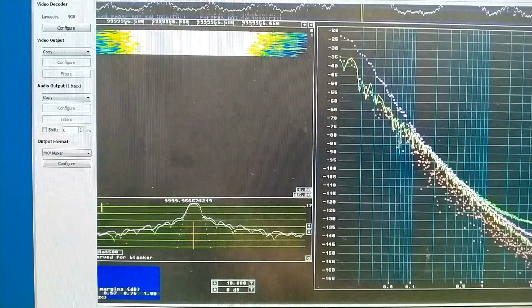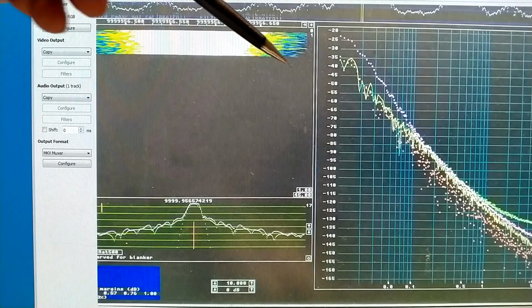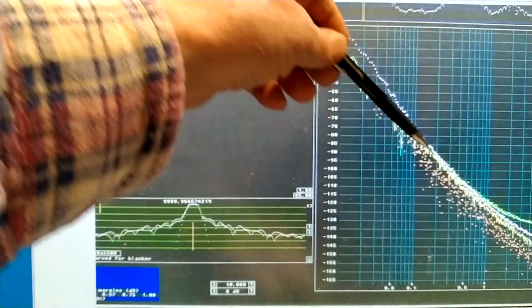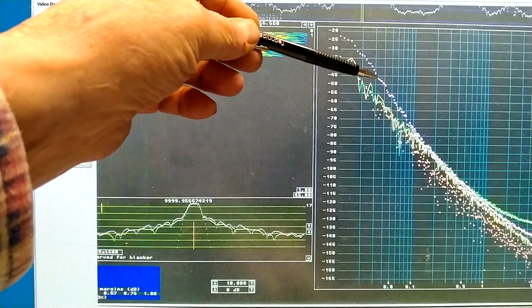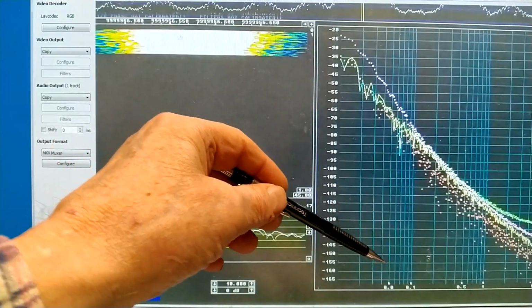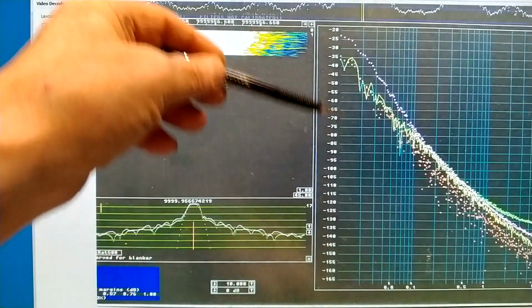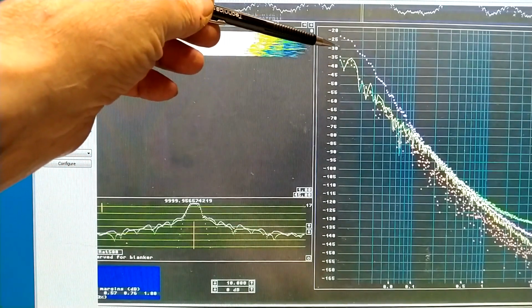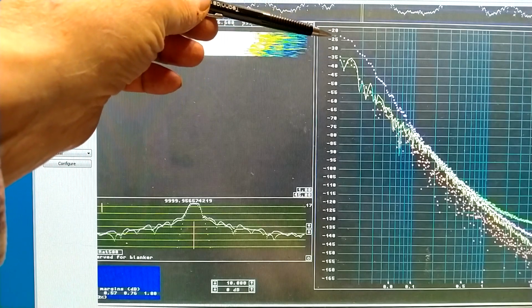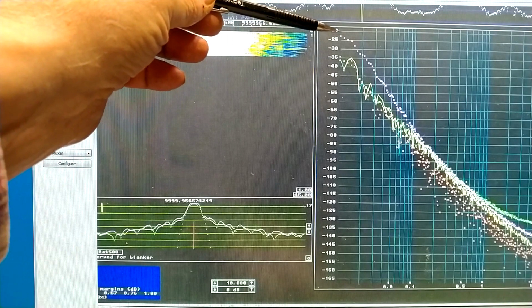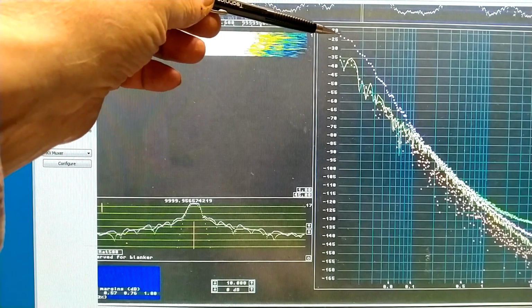Here is a typical result from when one oscillator was locked on the other. Meaning channel 2 was locked on channel 1 and channel 1 was free-running. And you can see the slope of the curve at 0.05432. One is at minus 35 dBc per hertz and the other at minus 22 or something. So it's a difference of about 12 decibels.